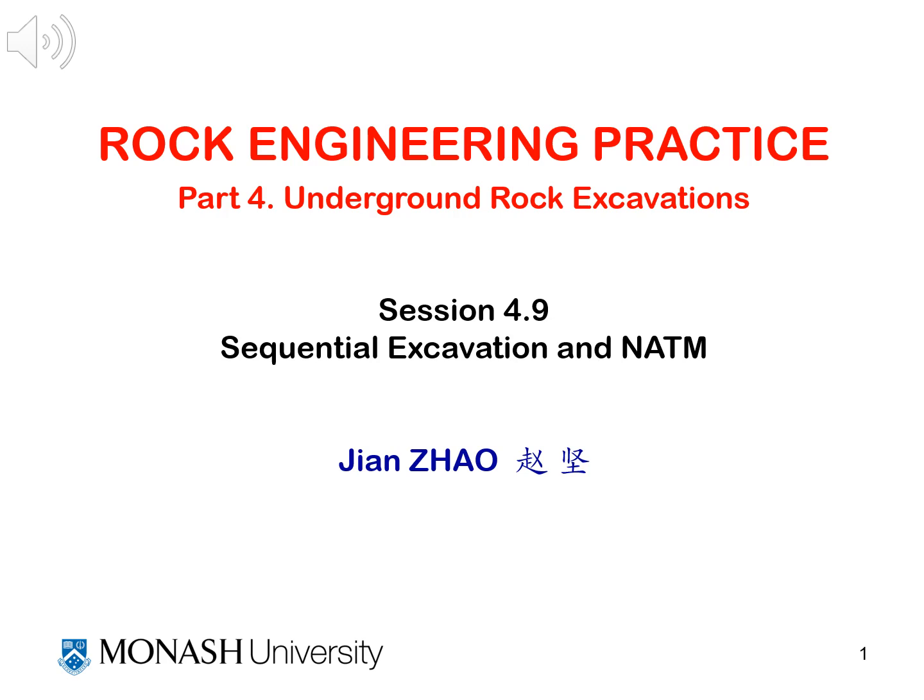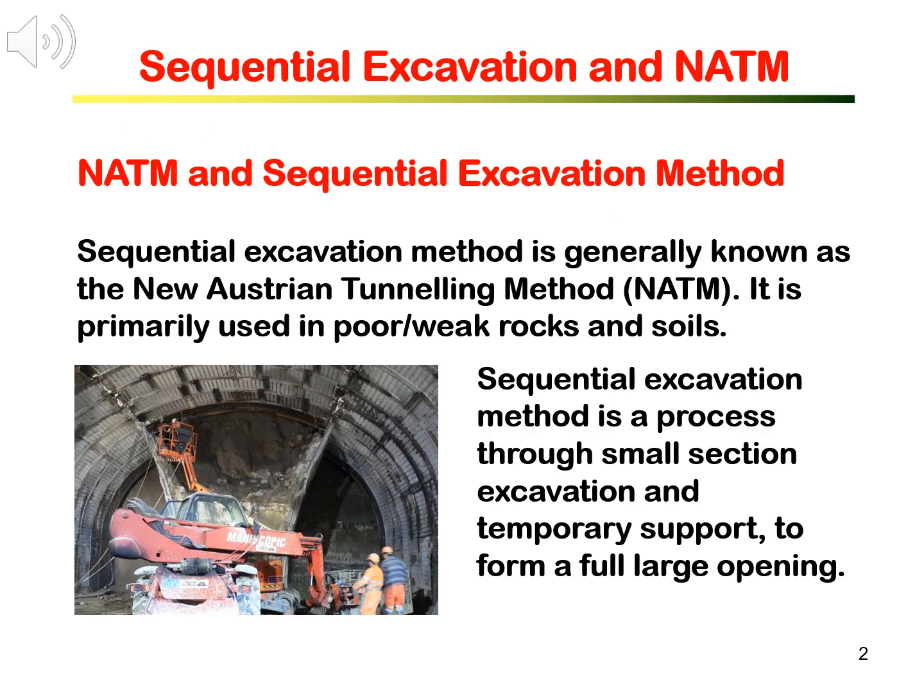In this session, we will cover the practical aspects of sequential excavation and the new Austrian tunneling method, popularly known as NATM tunneling. Sequential excavation method is generally known as the new Austrian tunneling method, NATM. It is primarily used in poor and weak rocks and soils.